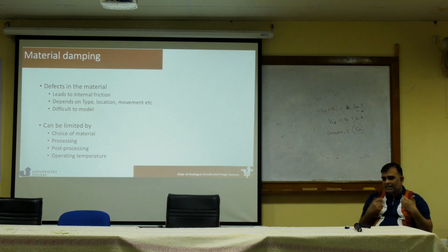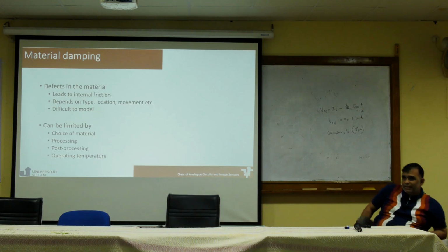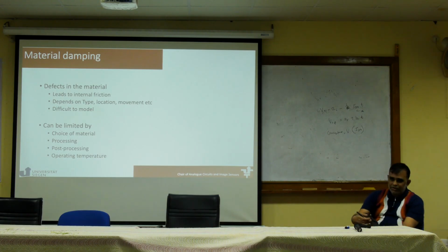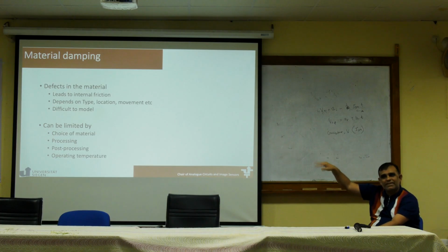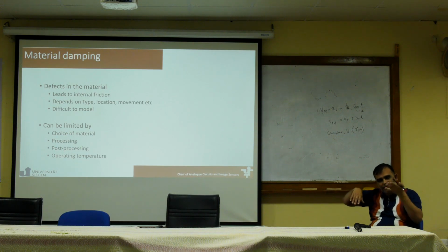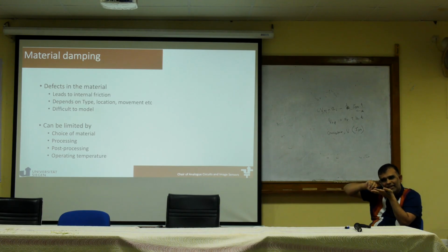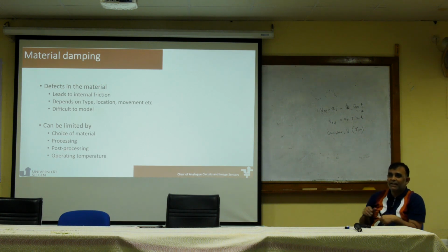So what we have seen is we can make a moving structure, but it causes quite a lot of issues in damping, and I learned it the very hard way. So remember, I made those resonators. The resonators were made to measure very tiny mass, and we could measure very tiny mass. On the things that were moving, we could deposit a small amount of platinum and then measure the exact amount of platinum just by looking at the frequency shift, and the device worked brilliantly.